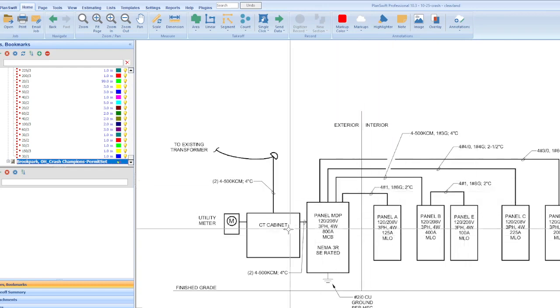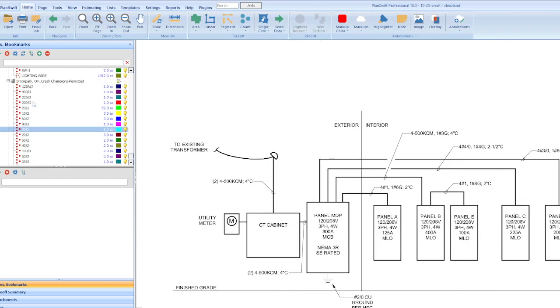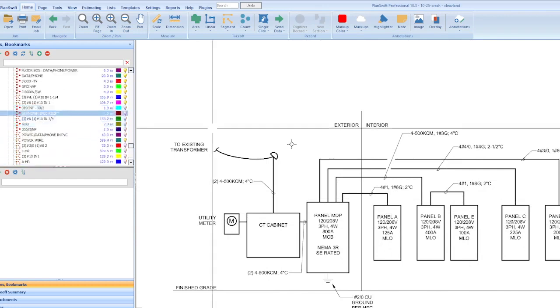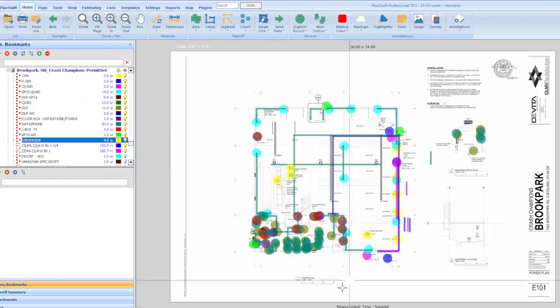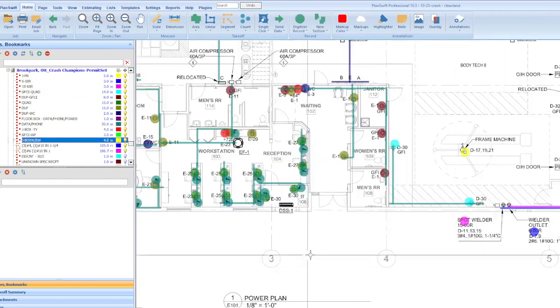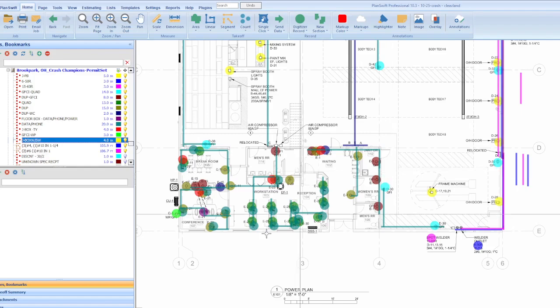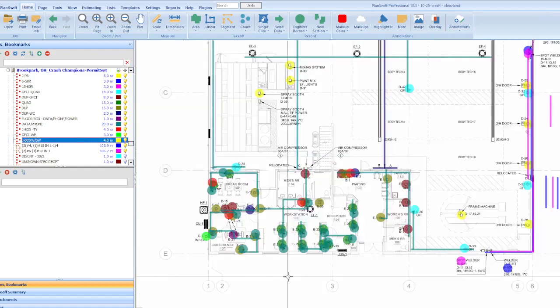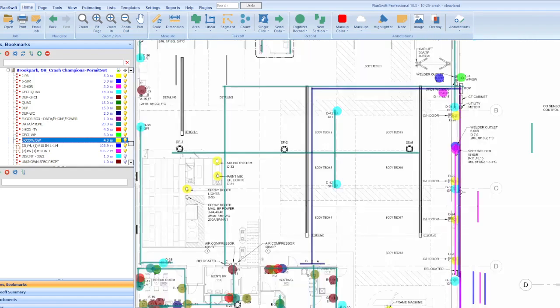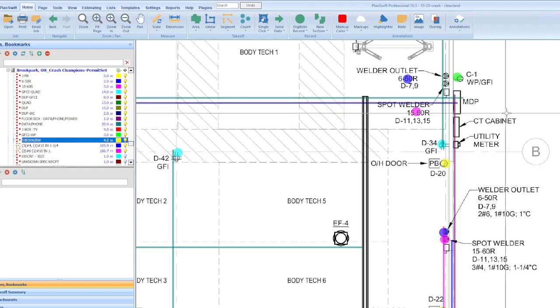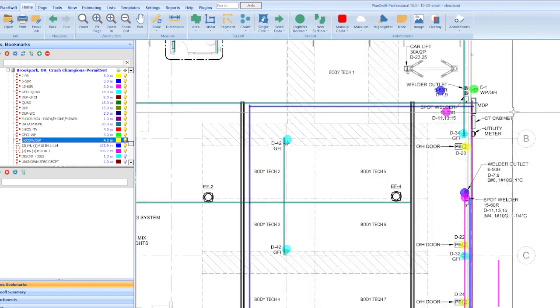I've got to figure out all of the physical distances for all of the power feeders to know the exact lengths. So where's the main distribution panel? We just saw it right here, so from there to all of the panels, pretty much.